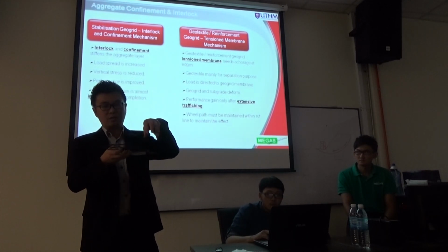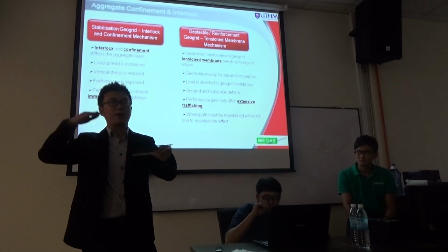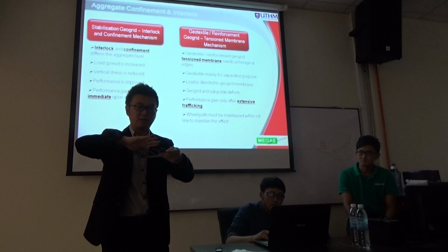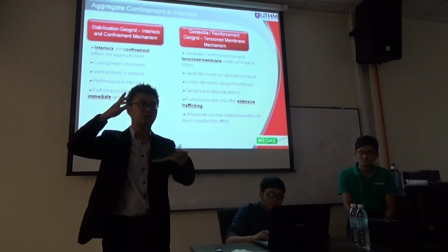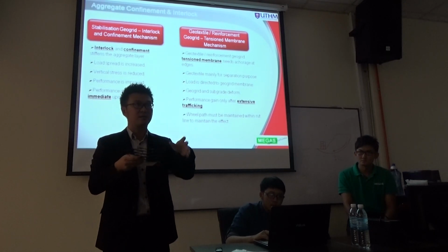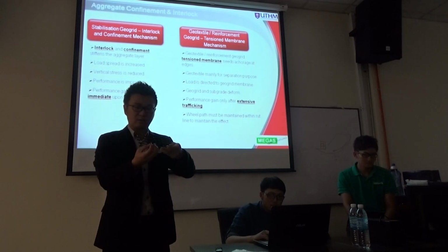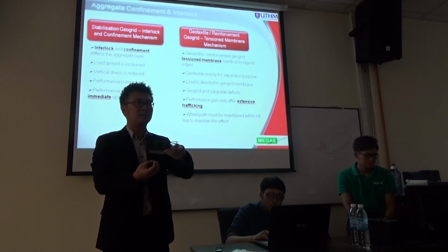You have to interlock the stones all together. So when there's a load applied on top of it, you will have a very good confinement to prevent the stone from moving sideways. Remember just now the causes of rutting, that slide? You will prevent the stone from moving sideways, to prevent it from settling down as well.